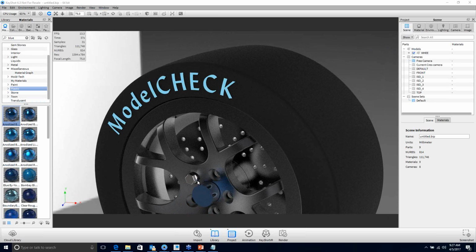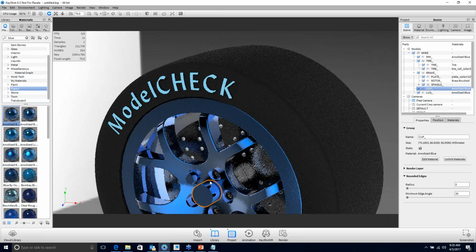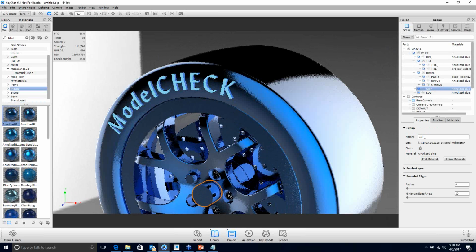If I want to copy the same exact material to another model, I can easily do that by, what's it called, I can hold Shift and left click to copy, and then hold Shift and right click to paste a linked material, right? A linked material basically means if I change this one material definition, both of these objects will change their material look as a result. So I can hold Shift and right click, that is linked. That's an easy way to pop the same material on many different parts.